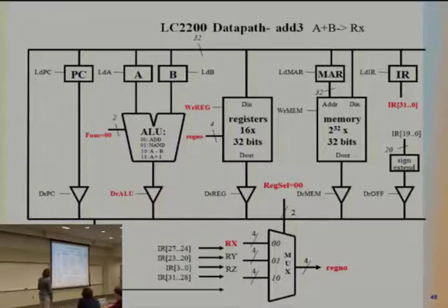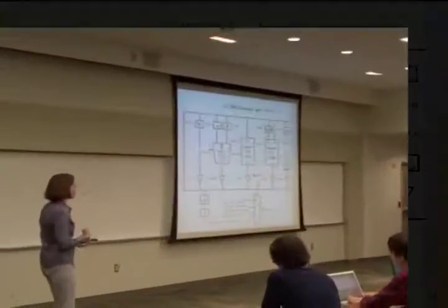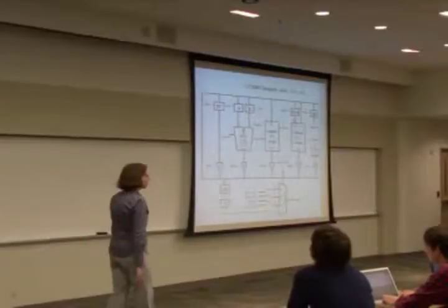How do we do that? Well, you select here that you want to write into RX by setting the register selector to 0, 0, and set then this address here and the write to 1, and that would be the place where the content of this addition will be placed. This is slightly more complicated, so if you have any questions, feel free to ask.